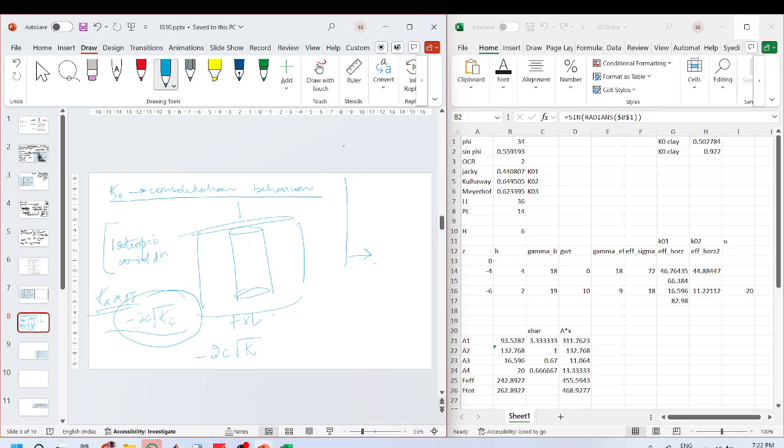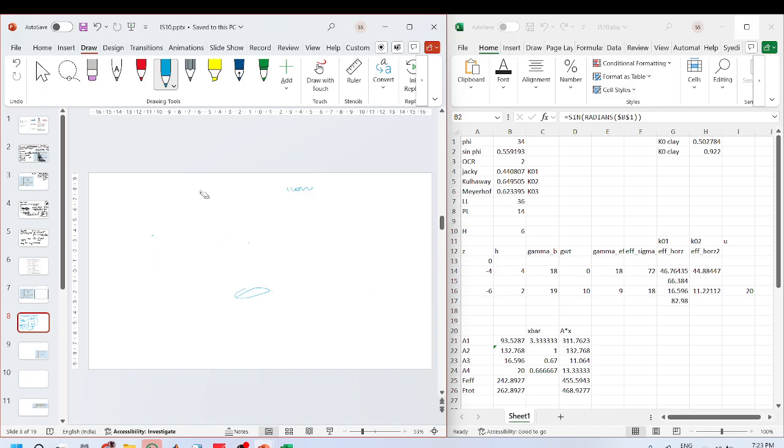In the passive and active earth pressure topic, that was the first time we talked about strain in the lateral direction. We have been focusing on stress in the normal direction, isn't it? Now, for the first time we are talking about strain in the lateral direction, which is in the active or passive state. And for K naught, there is no such strain. So that is why you will not see it explicitly talked about. Yes, ma'am. Okay.